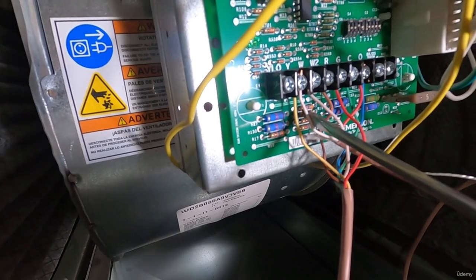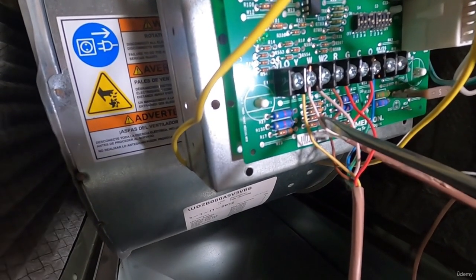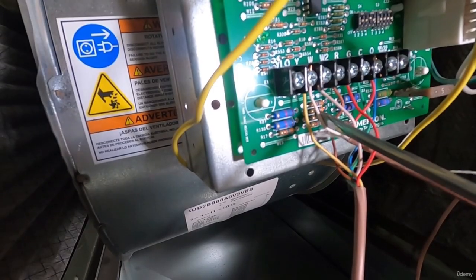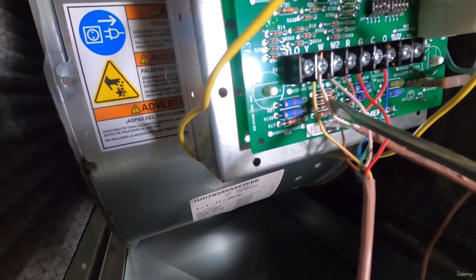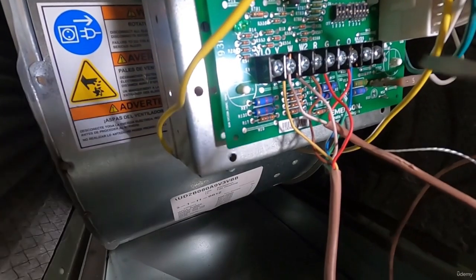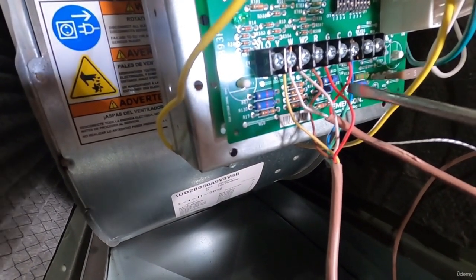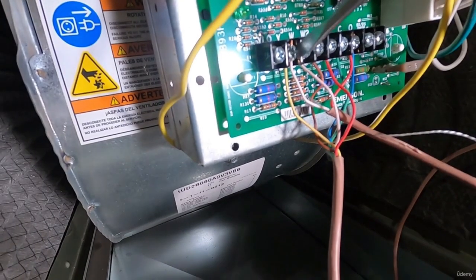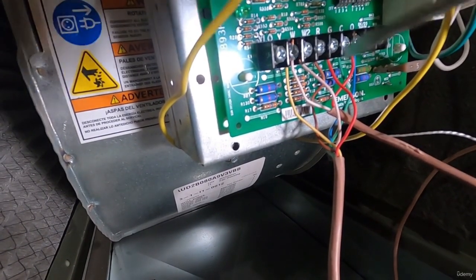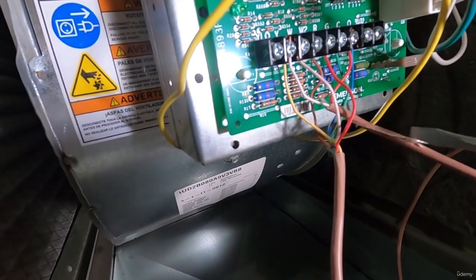And once 24 volts comes down from the thermostat to the Y, it's going to energize the condenser right away. The other side of the condenser wire, which is this one, the 2-wire, goes to common. That's basically your ground or your neutral. So once power is applied to the yellow from the thermostat, your condenser is going to come right on. There'll be a time delay, and then your blower comes on.